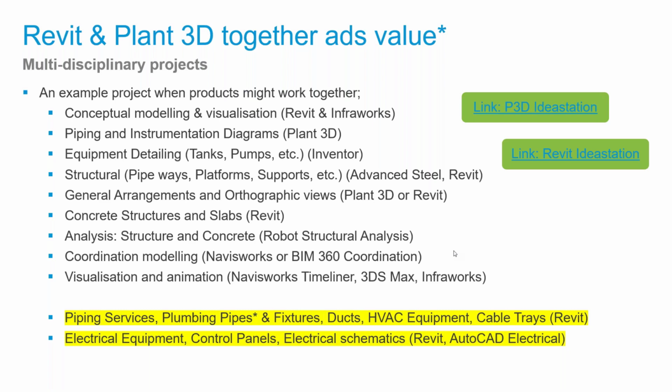So, for example, in Plant 3D, you want to make sure that you did unhide parts of the model, so you can see everything. Everything in your model will be included in the clash detection, so you need to verify this. You can do it in the review. You can also check if the steel representation is the correct one that you need to do a clash detection, and how you want it to display on BIM 360. And when you approve this workflow, and if it's set up like this, then the file will be automatically copied over on the cloud from the project files into the plans file. So this is one comment.